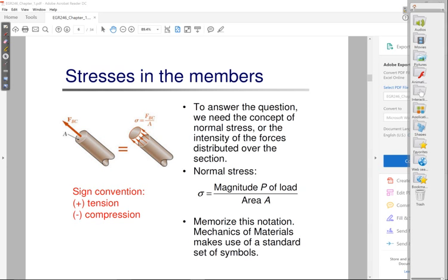All right, so going back to our definition of stress, this is what we call a normal stress. If you take a look at this word normal itself, another word that we can use is perpendicular. So normal stresses are defined anytime you have a force that's applied perpendicular to a cross-section. Anytime you have a force that's perpendicular to a cross-section, that force is going to be tensile or compressive. So normal stresses are always going to be tensile or compressive.